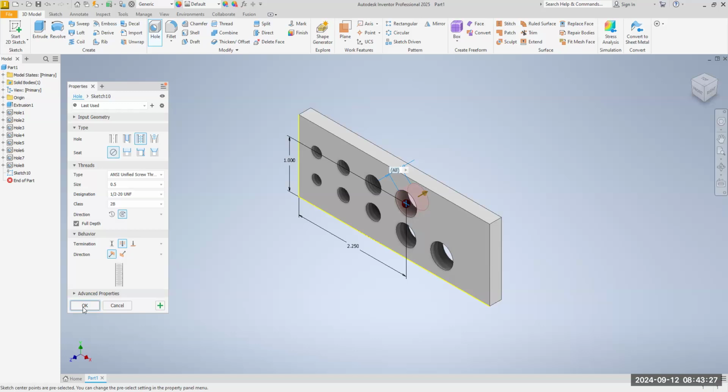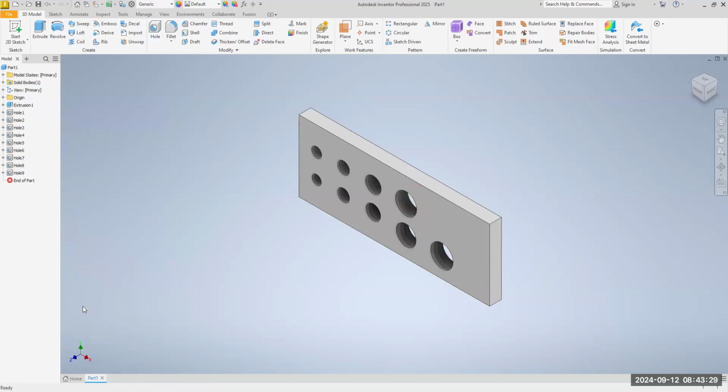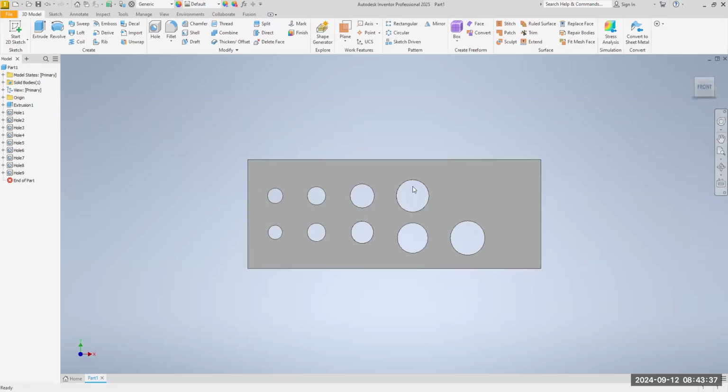Now, Mr. Morris made a mistake intentionally again this time with that hole. Here's what we need to do. That dimension is not 1 inch because if you look at it, it's on the same center line. This is not supposed to be on the same center line with these. So we go find that hole. Look, here's how you make the fix.